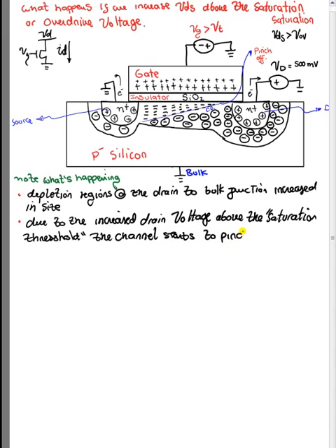What does that mean? Well, you can see from here. Before we used to have a channel that extended from the drain to the source, right? There were electrons all throughout that channel. Now the channel is moving a little bit too much to the left, and so now it doesn't reach the drain anymore. So that's what that effect is called, the channel pinching off, right?